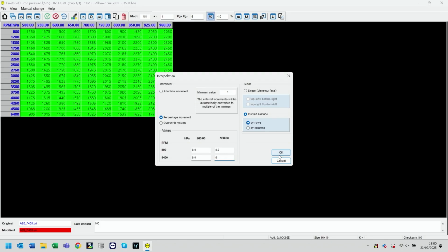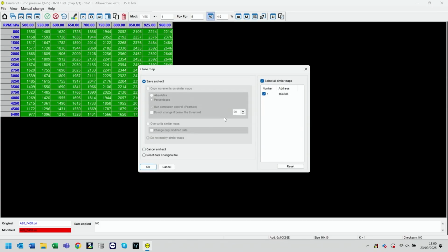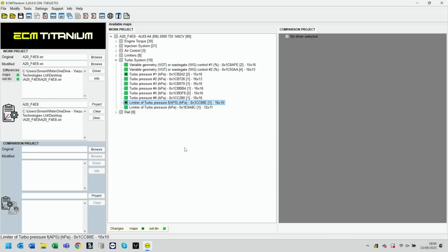I did see a hand go up in the corner of my eye. There was a question, I believe, Gavin? Yeah, this is from David. Why didn't you extend the injection time map for a larger dose of fuel? Okay, I think we made a change. I think we increased it by 8% on there, in line with the same change that we make into our turbo system.